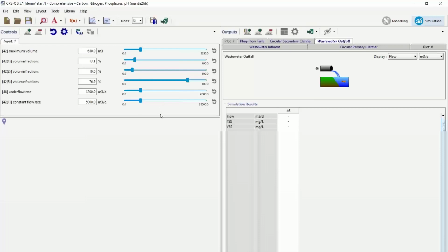All right, let's see if we can push it farther. So let's see if we can get this down even lower. Let's give it a little bit more of an anoxic zone to get more release before the uptake. So that means I've got to shave another 10% off that. And let's see how that goes. So are we still okay? 0.5, almost 0.6. Okay, well, we're still under 1. This is now dropping again. So that's gotten us below 0.2. And let's go just another 10% again, 30, 30, 40.